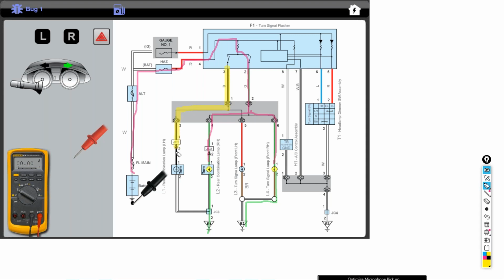So I'm going to go the positive side and the ground side in yellow, because it's representing the side that's not working. So the circuit's left-hand side is not working, and it would be possible to have two problems, two bad bulbs or two bad wires or two bad grounds, but the chances of that are unlikely. More likely, you look for an area of the circuit where one problem would cause both the front light and rear light not to work.